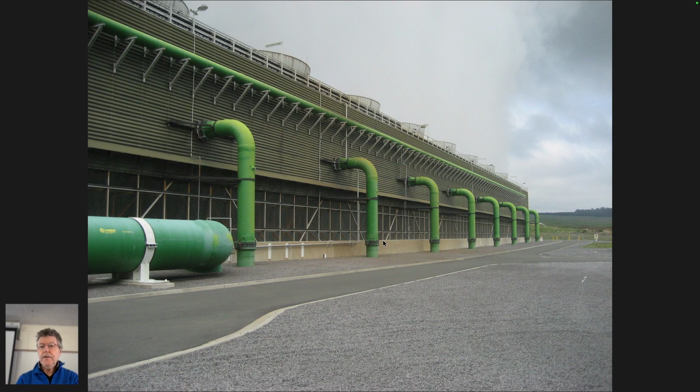This is Rotokawa, I think, one of the geothermal plants within the Taupo region. It takes steam that goes into these condensers. These are just turbine blades with cold water passing through them to cool the steam, and so under this curtain here is basically a continuous rainforest with water dripping down, which is caught and then re-injected into the reservoir.